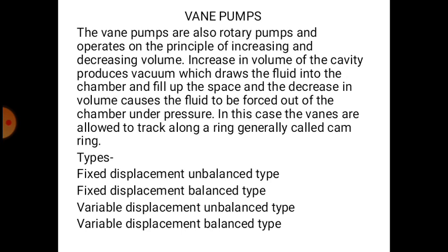So we have discussed the positive displacement pump. In all positive displacement pumps, as the volume goes on increasing, the suction is going to take place, and as volume goes on decreasing, the discharge is going to take place. So as volume goes on increasing, vacuum is created and it will suck the oil inside it, and when the volume goes on decreasing, the oil is discharged.